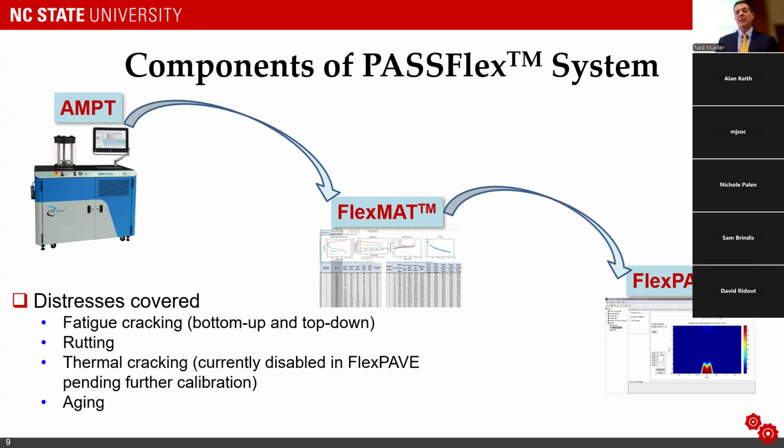These components in this system are trying to look at the major ways that pavements deteriorate, notably fatigue cracking that occurs in pavements over time, in combination with load repetitions, oxidation from exposure to the elements, as well as moisture damage and other physical factors that are causing deterioration, as well as rutting characteristics. These are the two main failure mechanisms and pathways we look at for flexible pavements, at least in North Carolina. We look across the U.S., especially in cold climate regions.